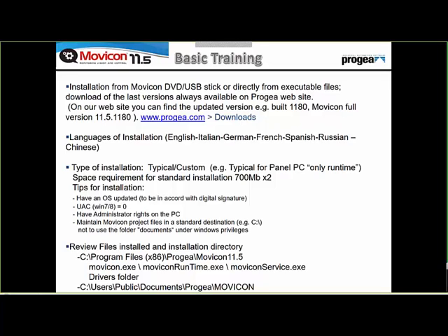Some general tips, not only for Movicon but for all software on this new operating system: make sure you have the correct access to the project resources. Movicon is a program that writes on files, so it requires the correct user level.